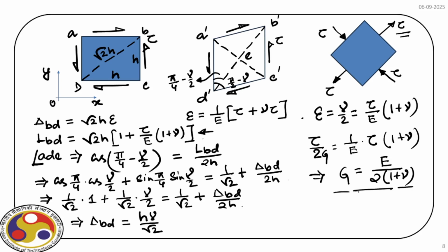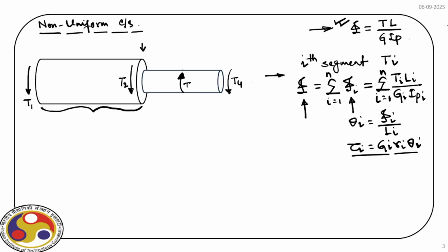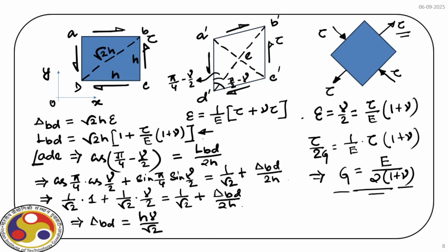This expression again we derived earlier when we correlated stress and strain at the very beginning. Today for the circular shaft also again we derived the same expression, and what we get today is the expression of phi, which gives us the value of G from the experiment, right? That we can again cross verify for the same material. We can cross verify with Young's modulus, right? Okay. So that concludes here.